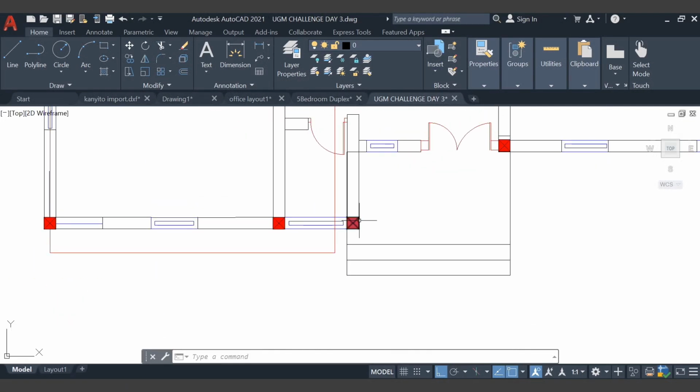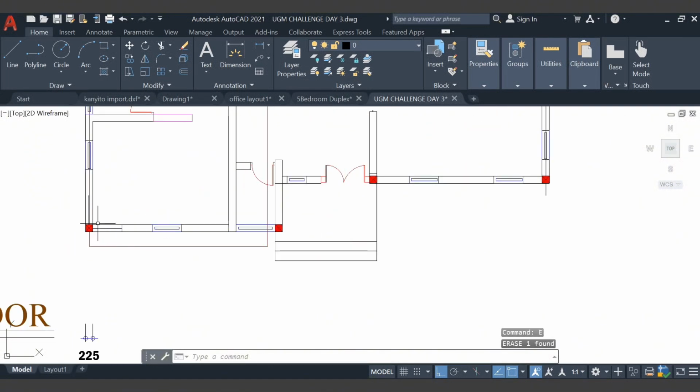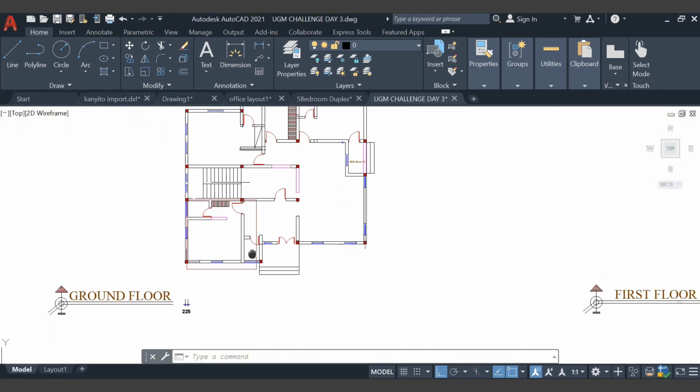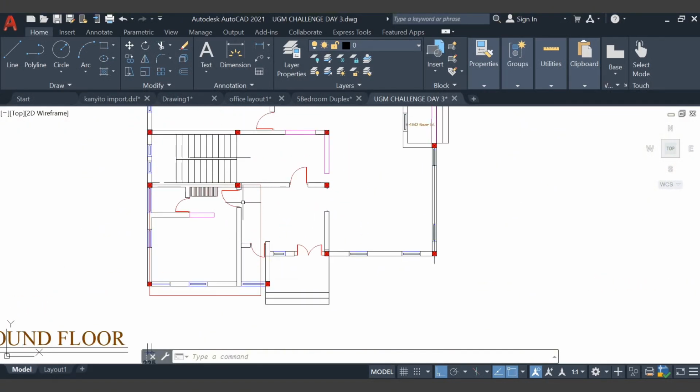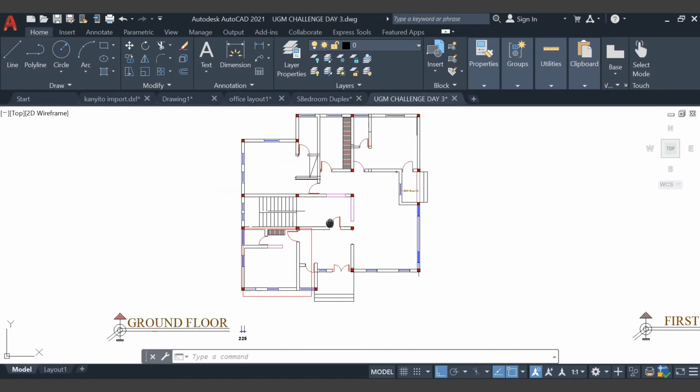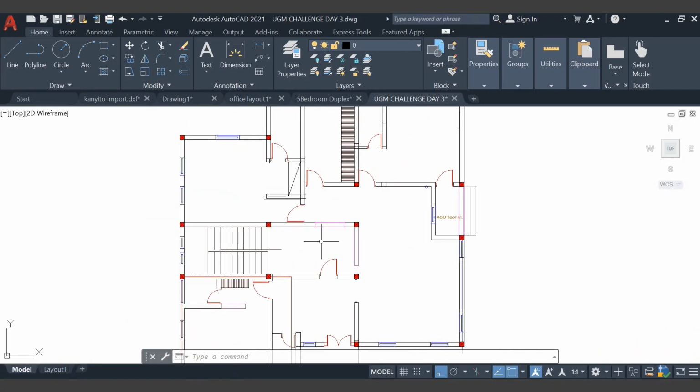But another option is you could also take this guy out, model, run your analysis, and see what happens with this beam. If it fails deflection, then you just need to increase the depth of this particular beam to about 600, and you know that every other beam on the project would be 450. They're just different ways to go about things. This is not one rule.